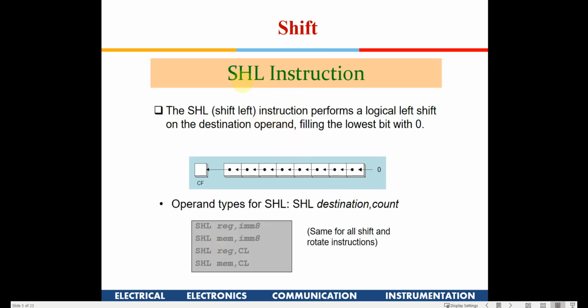Shift left instruction. Here is what happens. All the data will be shifted towards the left by 1 bit, and whatever is available in the MSB will be pushed into the carry flag. This is what happens when we write a shift instruction.